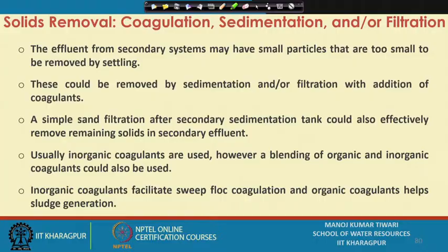Usually inorganic coagulants are used, such as salts of iron and aluminium. So, alum, ferric chloride, ferric sulphate can be used. However, at times a blend of organic and inorganic coagulants can be more helpful, and people use both together, as both have a different mechanism.